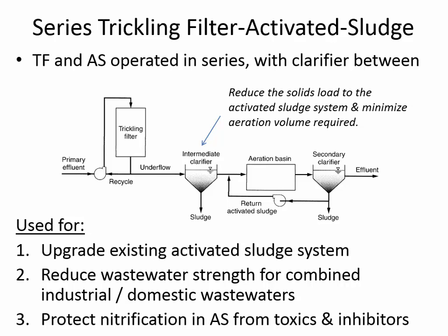And so this intermediate clarifier is always going to be like your A student, because the sludge solids settle really well coming out of a trickling filter. And so you get the benefits of everything that'll settle easily. You do that while you can, rather than introducing it into the activated sludge.